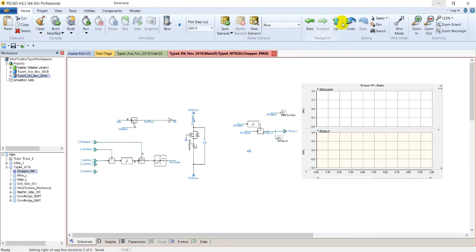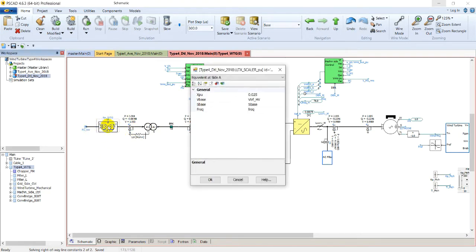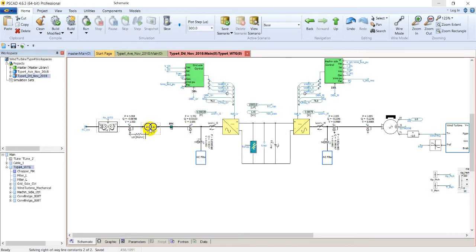So going back, AC filters are connected on both the voltage source converters to prevent some of the voltage harmonics of the voltage source converter from entering the grid and the permanent magnet machine. And there is this coupling transformer, a delta Y transformer, and this scaling command emulates a situation in which, for example, 100 such systems are connected to this grid.